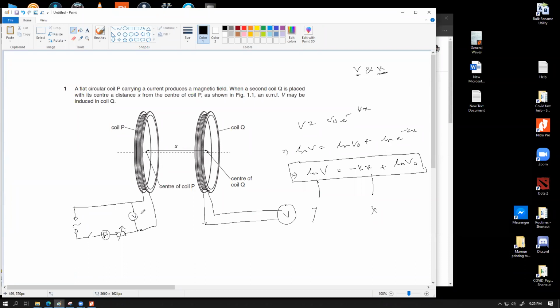So whatever you measure over here and whatever you measure over here, if you don't change the setup of your multimeter throughout your experiment, it will work out just fine. If you measure the exact same thing over the duration of your experiment, then your experiment will work out just fine. You cannot simply change RMS to maximum or maximum to RMS in random places. That's very important. When you keep your apparatus settings the same for the experiment, that's what matters. Ultimately, it would not matter.